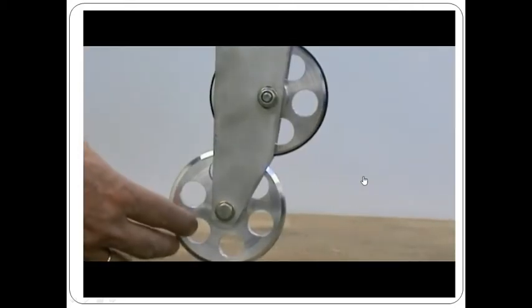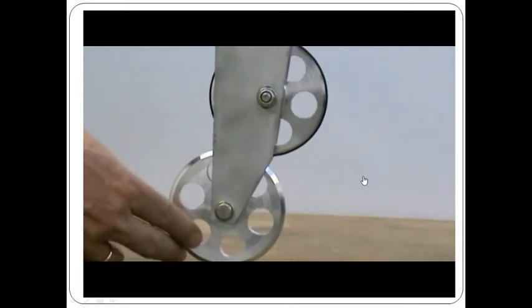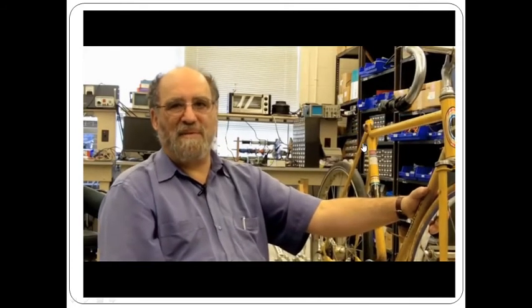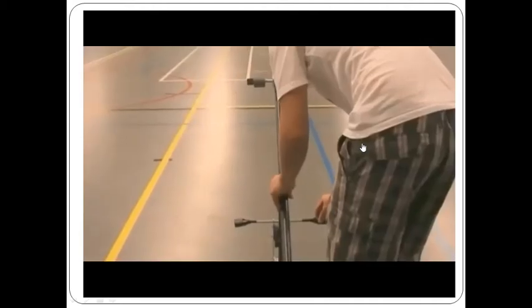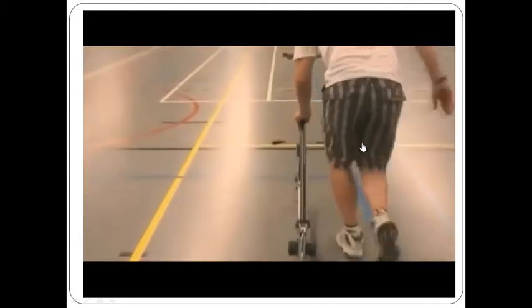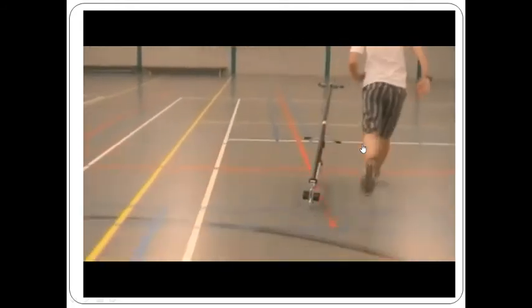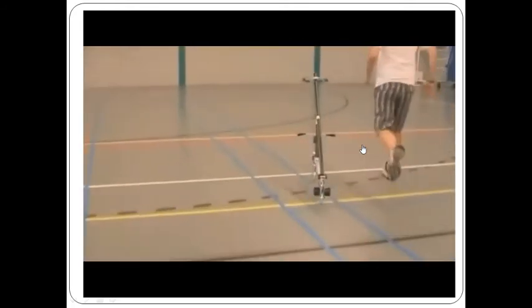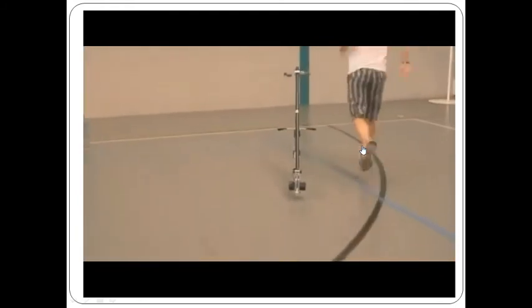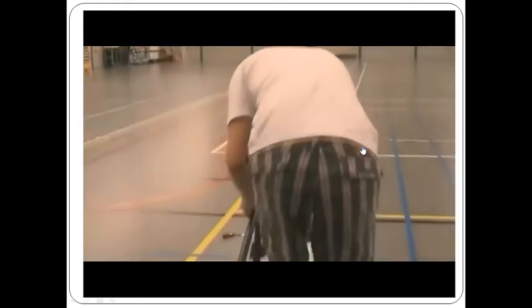The second front wheel doesn't touch the ground, it just spins backwards to cancel the angular momentum, and the second back wheel spins backwards to cancel the angular momentum. And it doesn't have this caster effect because it has the ground contact point actually slightly forward of the steering axis instead of behind the steering axis as in a conventional bicycle. And they pushed it, and it would balance itself, and they knock it sideways a little bit, and it would pop back upright, just like the calculations said it should do. It has to be that somehow leaning causes steering.